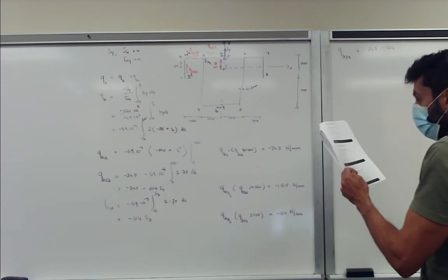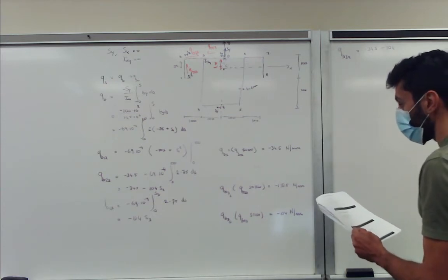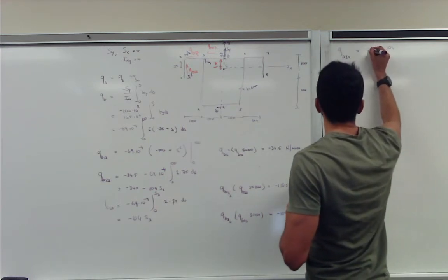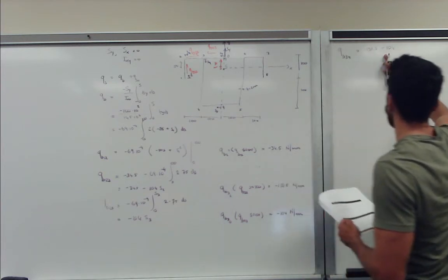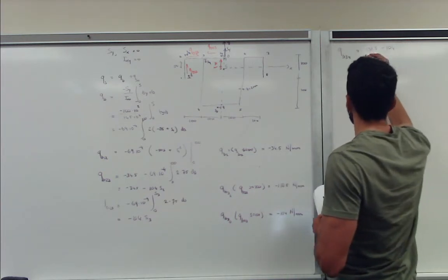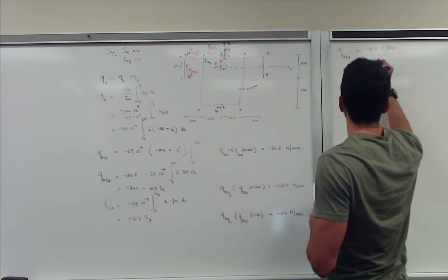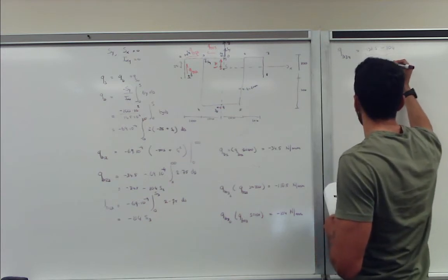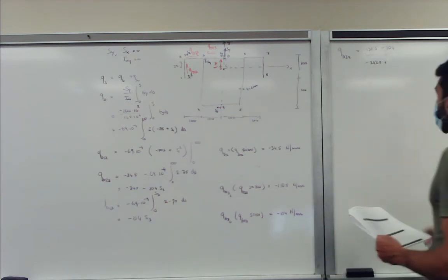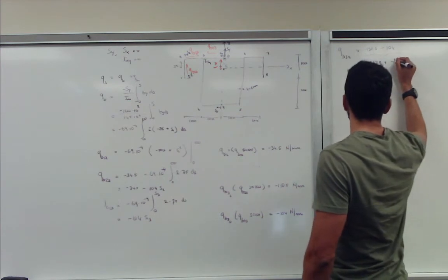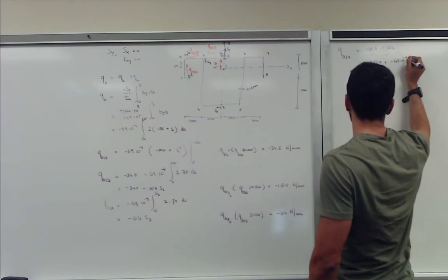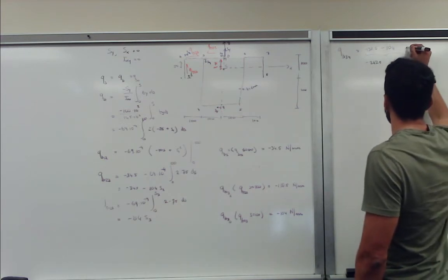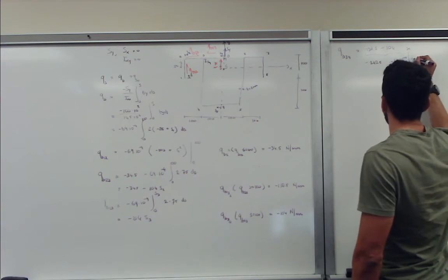Is that correct? Sorry, it was negative 138. So it's negative 138.5 minus 104, so this is basically negative 242.5, plus our regular shear flow. Again, from minus 69 times 10 to the power minus 4, and this plus becomes a minus because we have minus here, times the integral from 0 to S4 of t y ds.